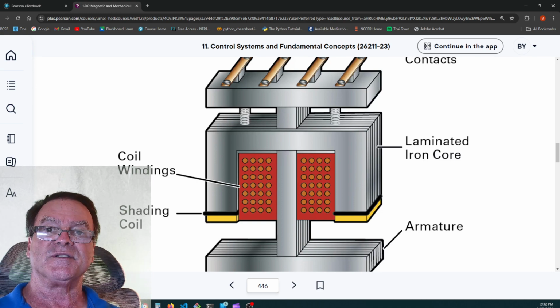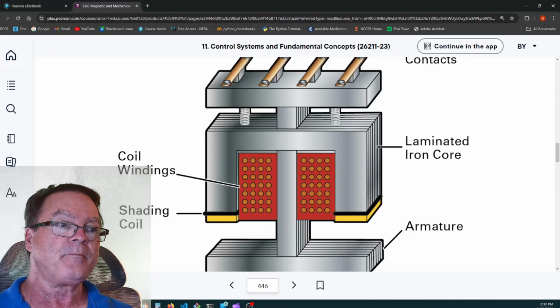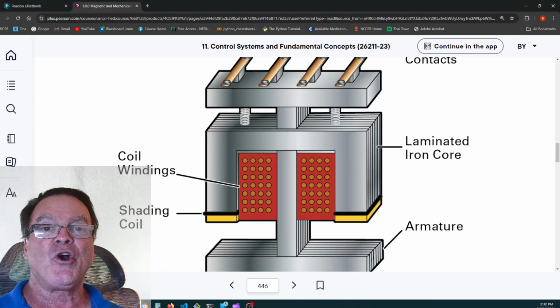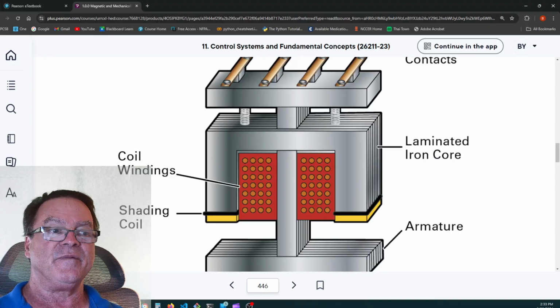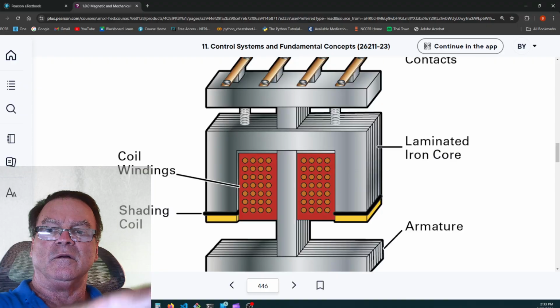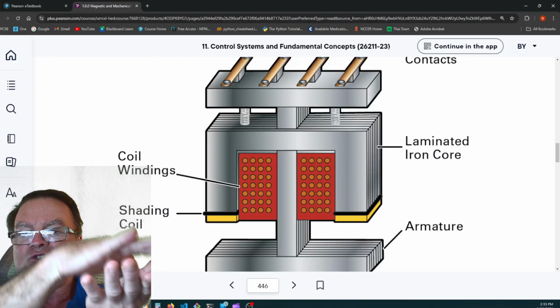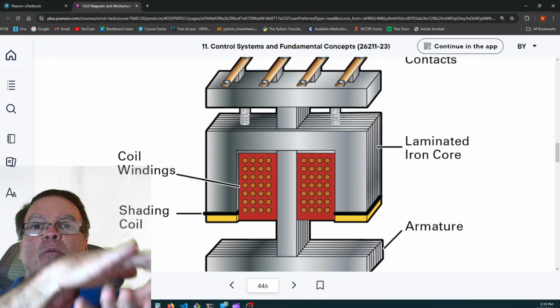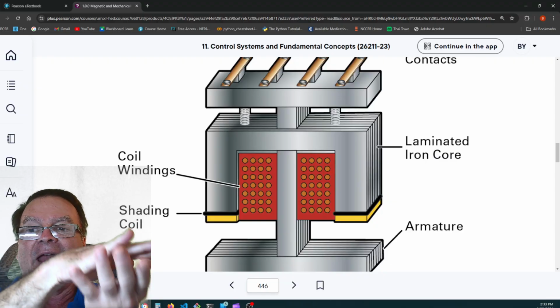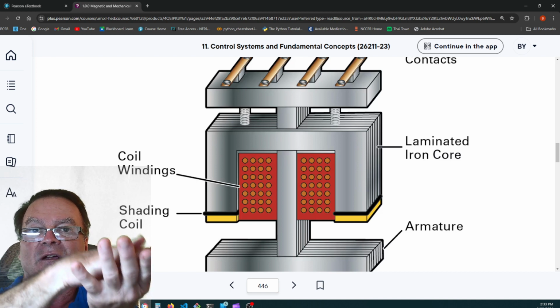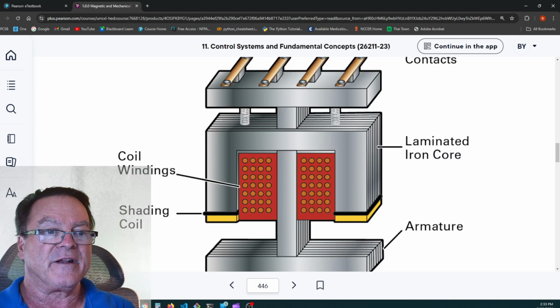As soon as it crosses the x-axis, as soon as that sine wave turns from one amplitude to start the second amplitude, that magnetic field will be returned, and the movable core will slam shut. So 120 times a second, this thing tries to open because of the spring, and it returns to a shut position because of the magnetic field.